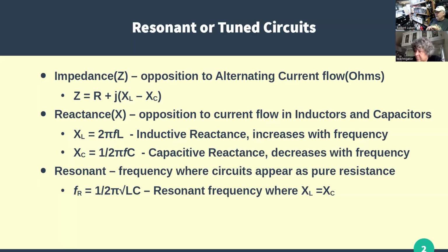We'll find out that capacitors have a high impedance at low frequencies, and it becomes lower and lower at high frequencies. So a capacitor at DC looks like an open circuit. It won't conduct any current. At extremely high frequencies, it looks like a short circuit.